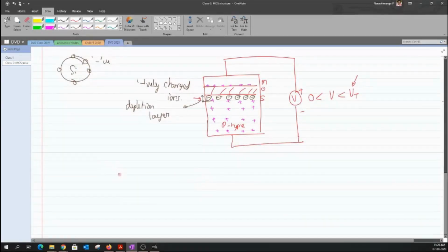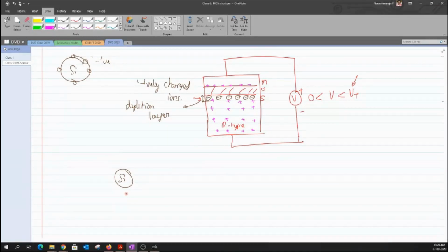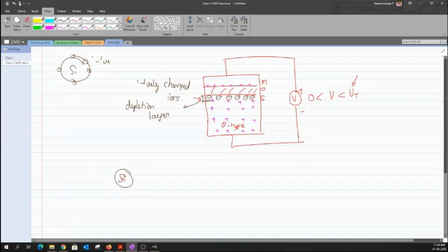Basically, in order to create a p-type semiconductor, we need some dopants. The dopant I need is generally trivalent. What does trivalent mean? It means the electrons in the valence band would be just 3. But a silicon atom requires 4 valence electrons to completely form covalent bonds with its neighbors, so this leaves out holes.